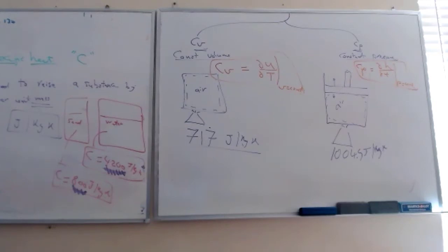However, I recommend please to use Kelvin. Do not use Celsius. Always use Kelvin to be consistent. Because when you use the equation of state, the ideal gas law, or other equations, the temperature needs to be absolute temperature. Do not use any Celsius, please, unless you are using the table, the steam table. You go with Celsius, input and output. But when you use an equation, please stick to Kelvin, absolute temperature.